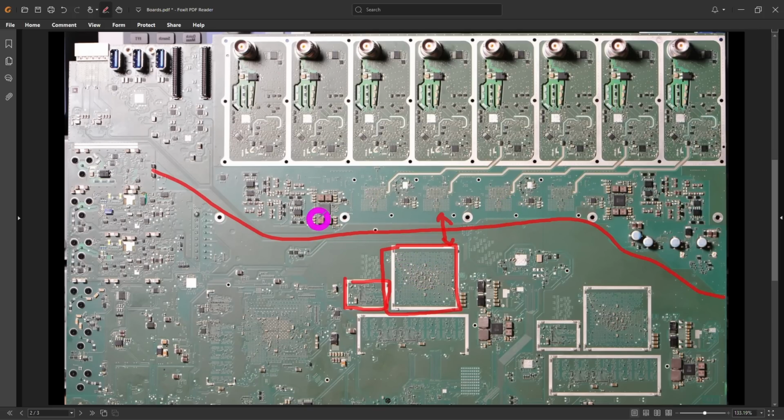A lot of DC-DC converters, every time you see a cluster of inductors and capacitors, you do have a voltage regulated DC-DC converter section. If you also look carefully, you can see all the connectors that the user interacts with have individual screws holding them solidly to the board. First, this makes them easy to replace and also makes them really mechanically stable because the user is plugging and unplugging things into all of these BNC connectors.